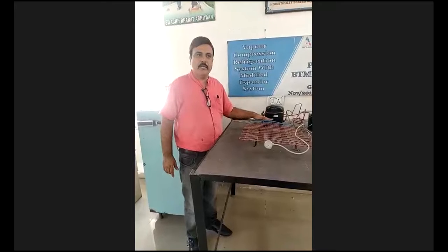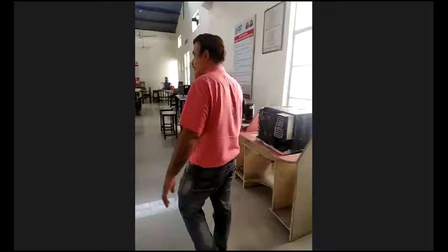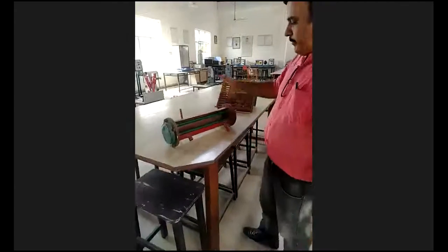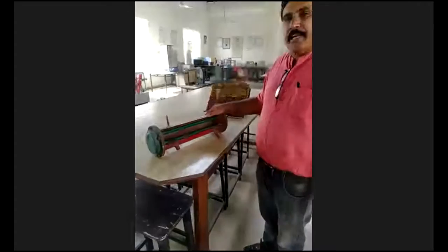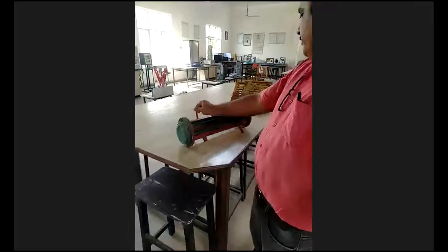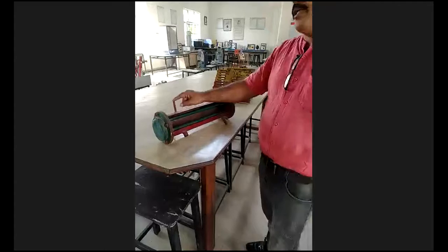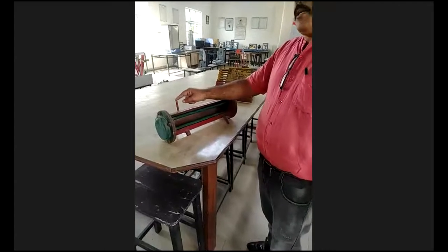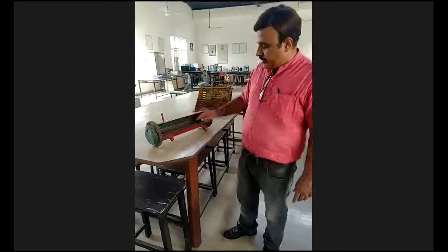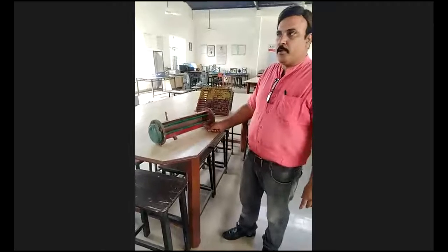And then this liquid refrigerant is again supplied to the expansion valve. Next, we have the sectional model of the shell and tube type of condenser. Look here: the refrigerant is coming from the upper side, from the compressor, and it is flowing. The refrigerant is supplied to the expansion valve at the bottom through this hole.